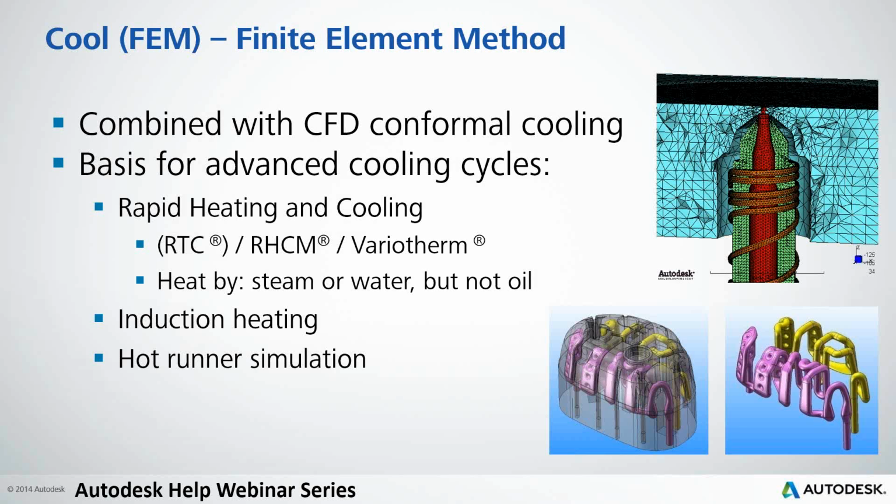I heard some customers started to ask about this, but the main reason is that usually the same channel is used for heating and cooling, and if we are using steam, the steam is not cleaning the channel from the previous oil, and if we are using water, the water gets dirty with the oil. So this is something that we are not able to simulate nowadays, but we could combine hot steam and cool water. Also induction heating and hot runner simulation, as we could see in this picture.